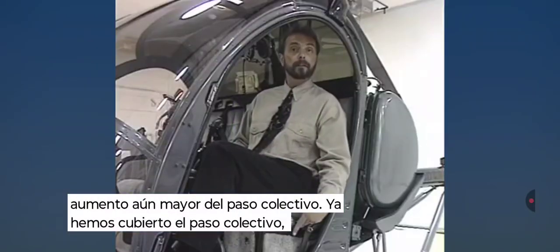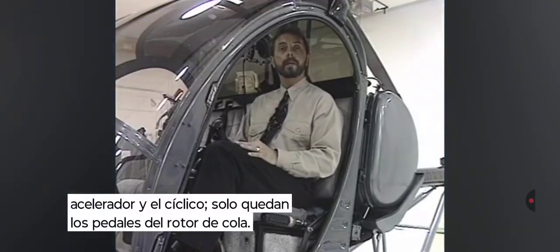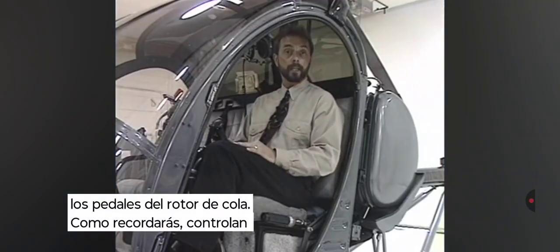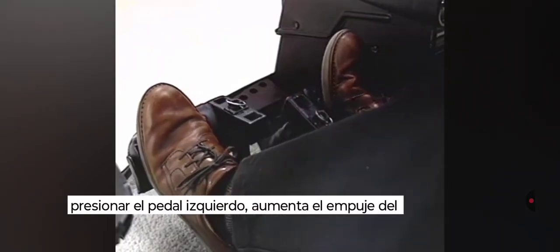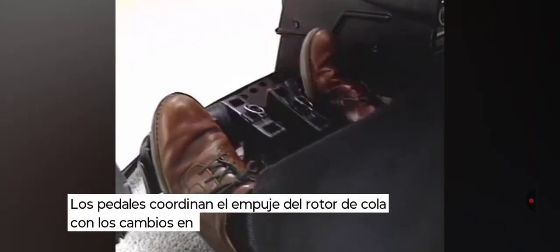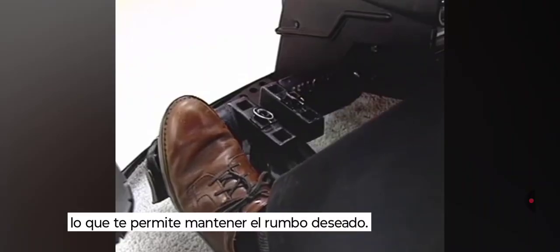We've covered the collective, the throttle, and the cyclic. That just leaves the anti-torque rotor pedals. As you recall, they control heading by regulating the amount of thrust that the tail rotor produces. Pushing left pedal increases tail rotor thrust. Pushing right pedal decreases tail rotor thrust. The pedals coordinate tail rotor thrust with changes in main rotor torque, enabling you to maintain the desired heading.